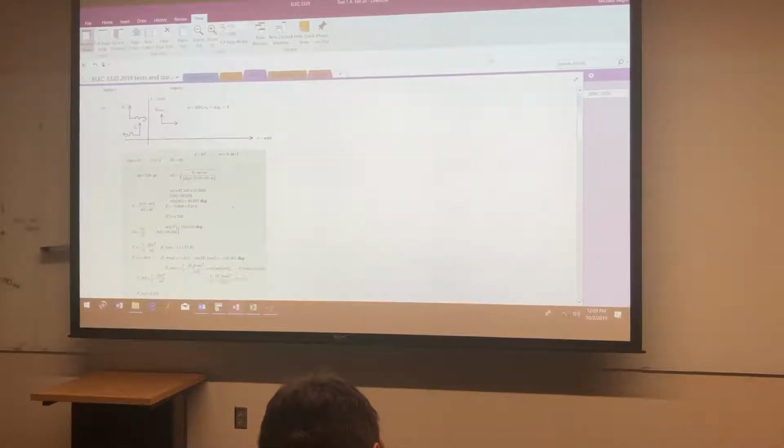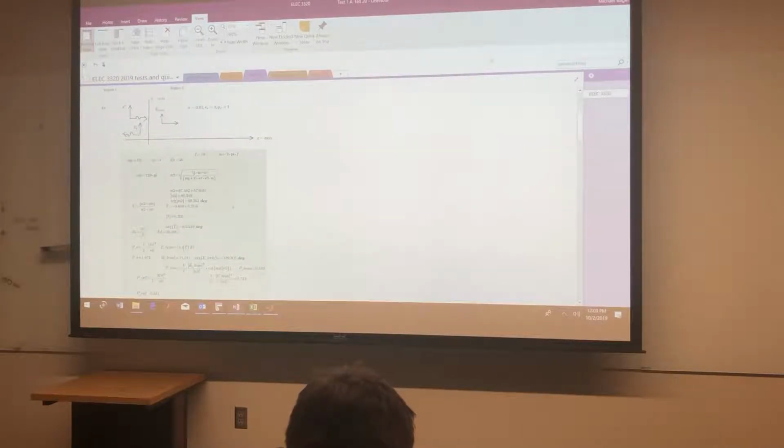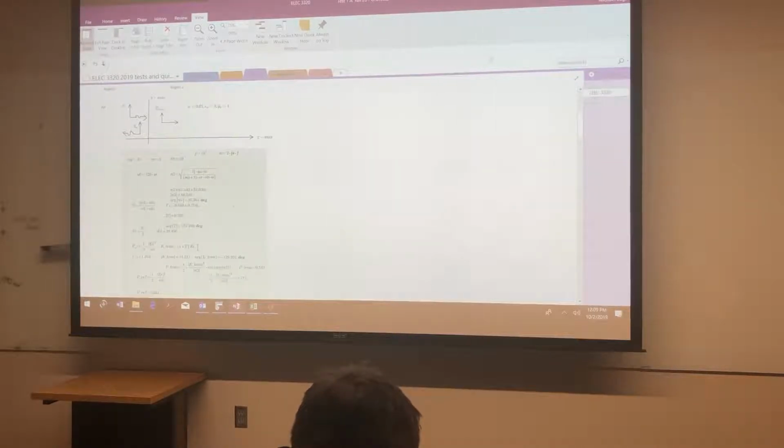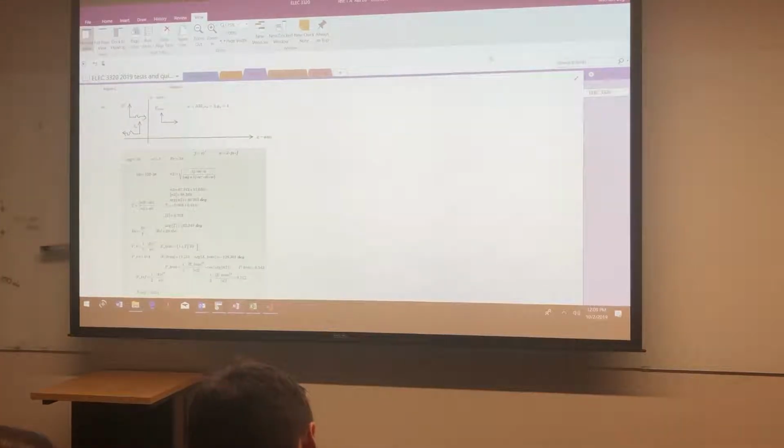It was not meant to be a hard test in any way. These are straightforward things. Your calculators, you get eta 2, you calculate gamma because you have eta naught, it's 120 pi. Then after that, you get the incident electric field. Now, the transmission coefficient is 1 plus gamma times the incident field. It's just tau is either 2 eta 2 over eta 2 plus eta 1, or just 1 plus gamma. Do you all follow me on this class?